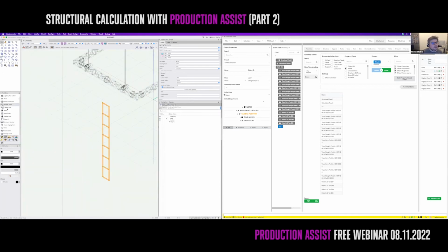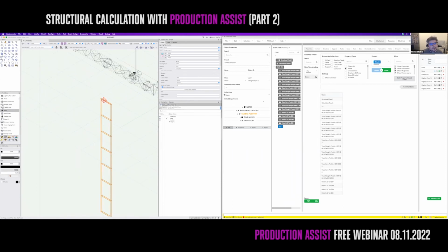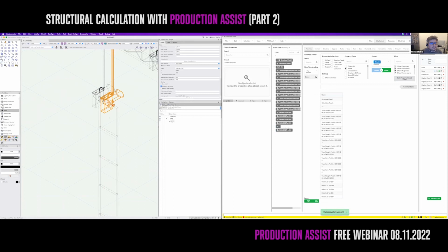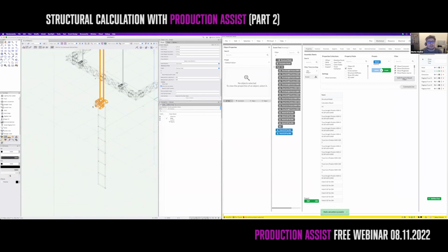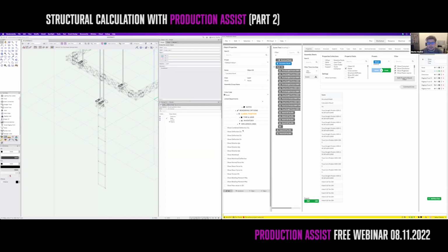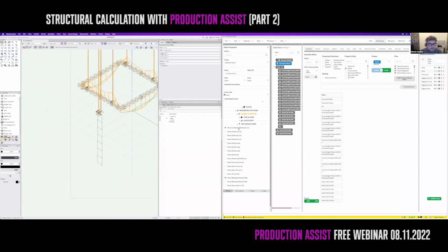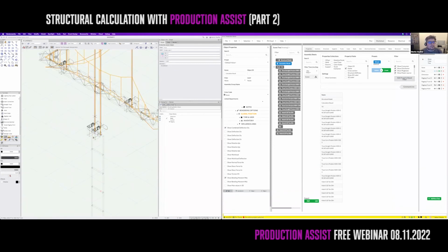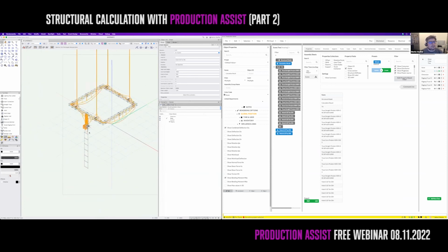The next step is inserting hoists. So I'm using the hoist tool and inserting 1 hoist over here and 1 hoist over here, so that I have 2 hoists actually supporting this, so that they can be calculated. It's working out of the box. So if I'm adding in here now the bending moment and the combined deflection, you see that the top truss is calculated, but the bottom one is also going into the roof. To change this, select the two hoists in here and set the high hook height to 0, so that it's connected with the actual truss. You see in here right now, it has connected these two things and the actual lightning pipe ladder.